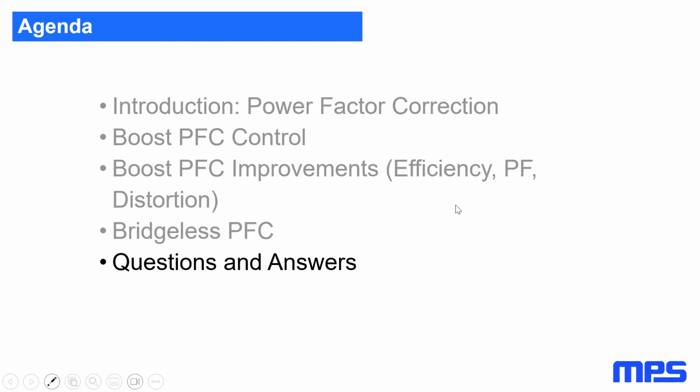Now the V-in sense can be rather simple, not necessarily very complex internally with a multiplier and everything, because if you're running a totem pole in constant on-time CRM, then you can probably get away with a simple architecture. But you still need that V-in sense anyway, at least for the selection of the MOSFET, unless you decide to not use MOSFETs but use diodes instead. But in that case, it will not be very interesting.